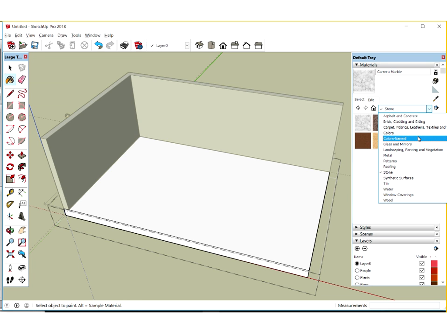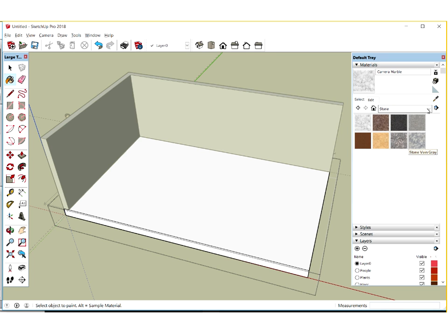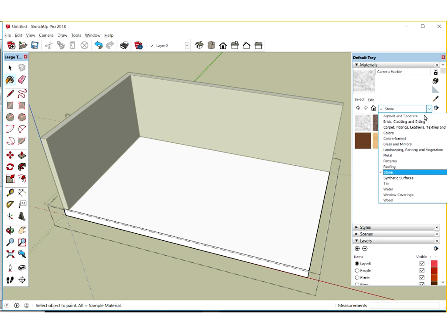We will look in a future workshop at importing materials as well. The SketchUp library has some good textures, but it's limited, but it's easy to import under the file menu and import good quality JPEGs or other types of image formats to use in your models. So for this floor, you'll find the timbers are very limited in the SketchUp library. So maybe we'll put a stone or maybe even a concrete type texture. There's a couple of asphalt and concrete textures in there.